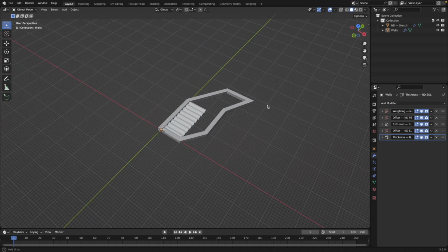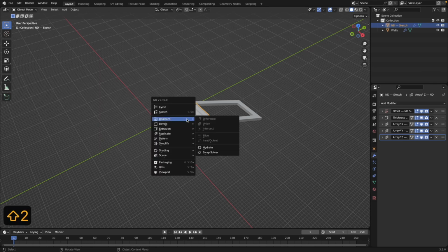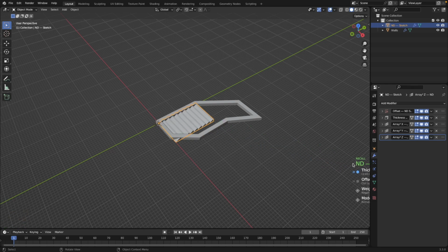So now this is the shape that we're trying to fill in with a part, and we want these fin pieces of our vent to completely fill this thing out, but not to stick out from the edges in an unsightly way. And so we're gonna start actually by making them stick out from the edges, because that's the easiest thing to do. So we'll select them all, and the first thing we need to do is change our solidify modifier, because they are obviously not wide enough to fill in that space.